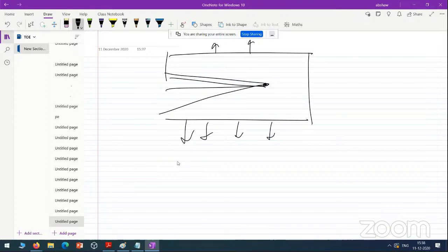Then another question is the plane stress and plane strain problem. When you say plane stress, it means that your stresses are confined in a plane, right? So if you have x, y, z axes, then you have components of stress only in the x-y plane.